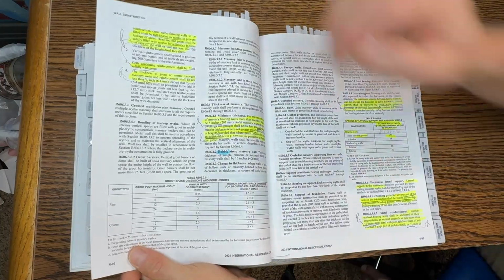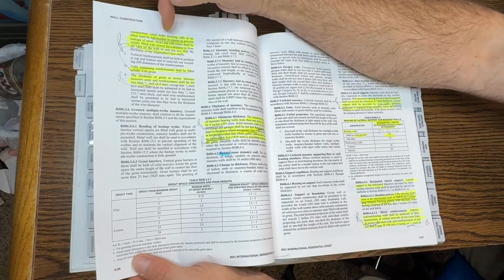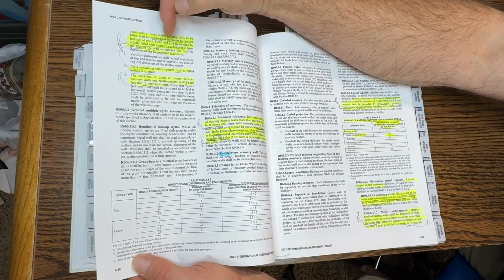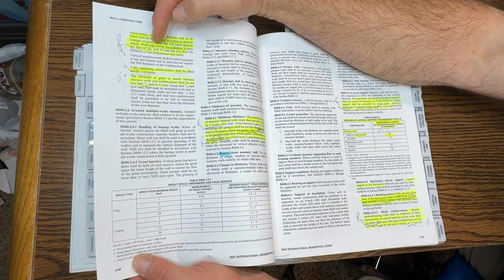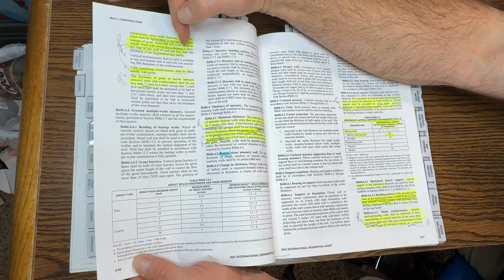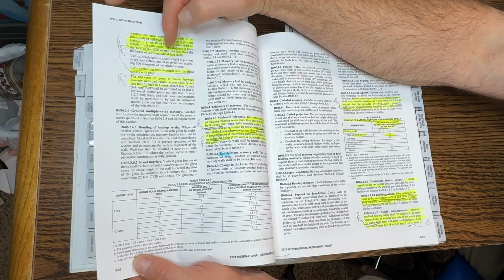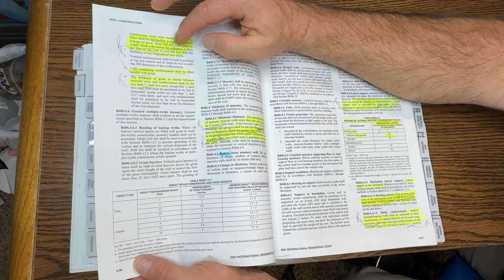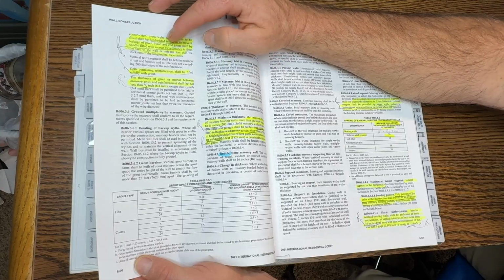In partially filled construction, cross webs forming cells to be filled shall be full bedded in mortar to prevent leakage of grout. Head and end joints shall be solidly filled with mortar for a distance from the face of the wall or unit not less than the thickness of the longitudinal face shells. Okay, so that is item 1.